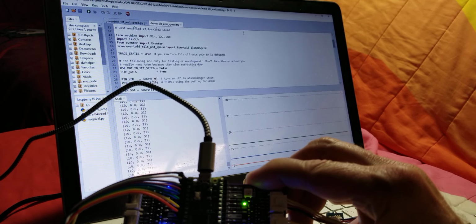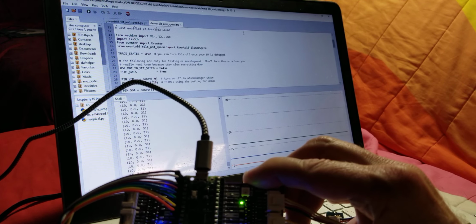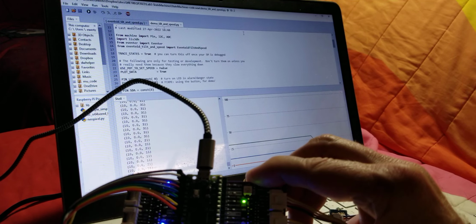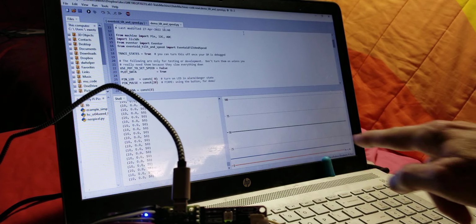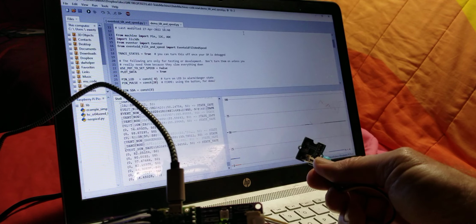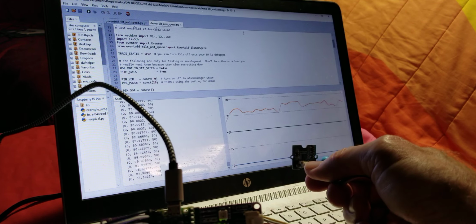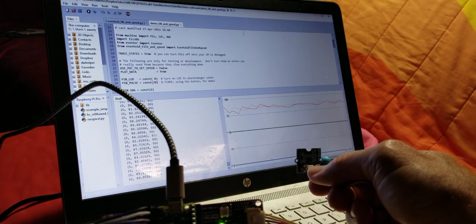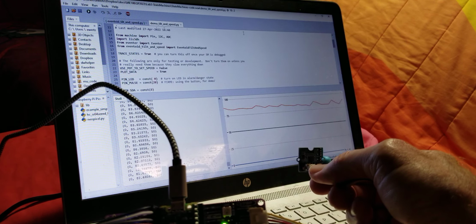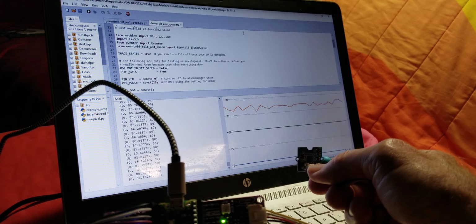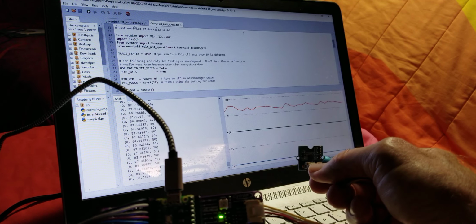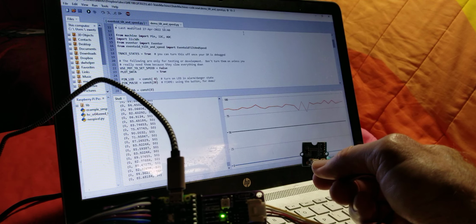Tell you what I'm going to do. I'm going to leave the speed fixed at 30. And now let me bump it up to 50, just to get it in the middle of the plot. And the blue line, which is down here at 10 right now. Oh no, the state line is at 10, I think. Let me grab my accelerometer and get it oriented. Okay, so right now my speed is 50 and my tilt is 90. So this is a safe operating condition. I'm not exceeding the speed for which the current tilt is unsafe.